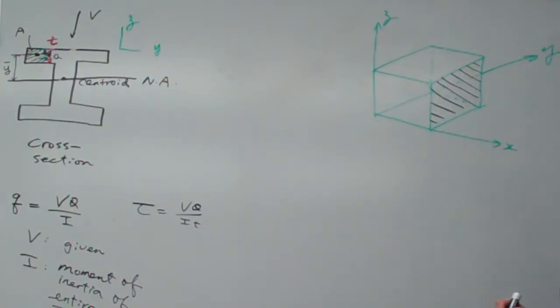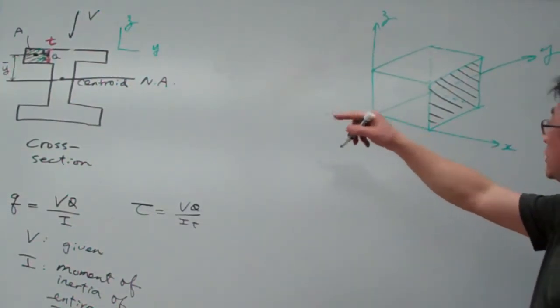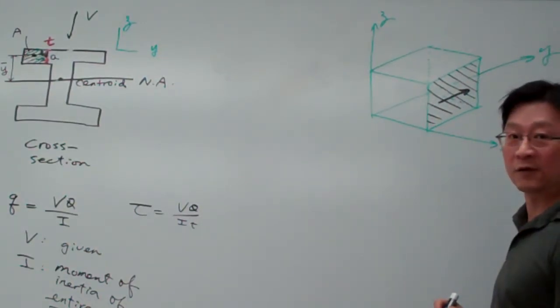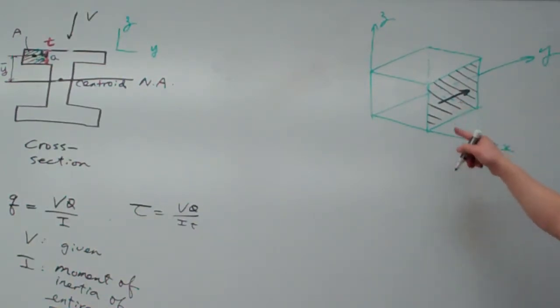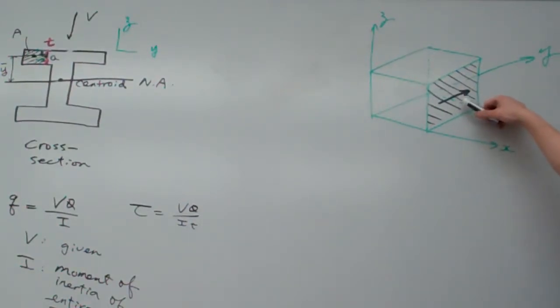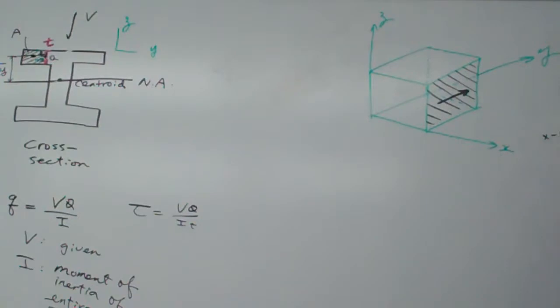Right? Okay. On this side, we have the shear stress in this direction. So clearly this one is on here. And per our notations, tau, if you remember our notation for this one, this is the shear stress in which plane? In the plane that has a normal to x and pointing to y direction. The first symbol is to symbolize the plane. So that is on the x plane pointing to y direction. So this is tau xy.